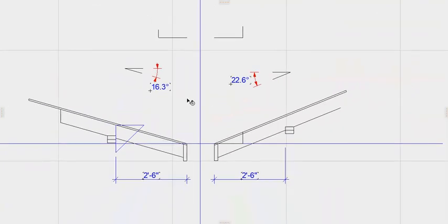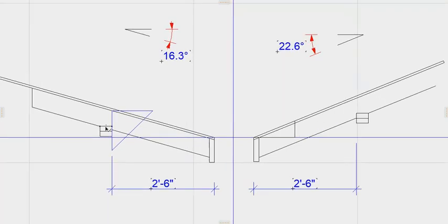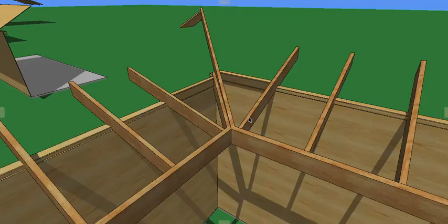So that gives you a sense of how the speed square helps you out there, and how you would do the common rafters to get those to align. And what you'll notice is you have your top plate here and your top plate here, and you can take your parallel line here and figure out the difference in height of your two walls. So that sets you up for that part of this.